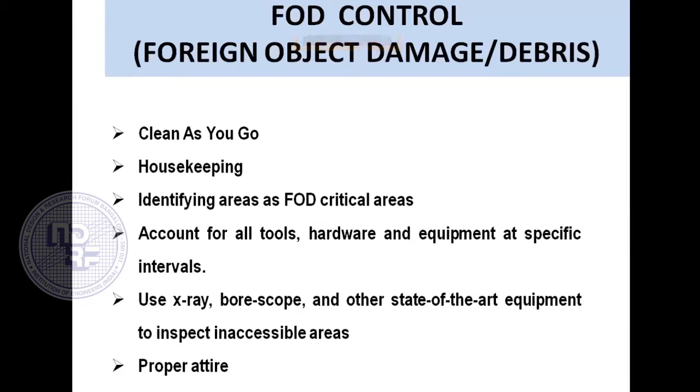And another important thing is that the people working wear proper attire. Attire means, you have seen people in the aircraft industry, not only aircraft industry, again going back to the automobile industry also, people working with coveralls. These coveralls are a specific attire for the aircraft industry to ensure that whatever tools or whatever small items are used, there are several pockets in this attire which help people to store pens, small mirrors, everything, so that nothing spills out and falls onto the aircraft or into the cockpit where it is not supposed to fall.